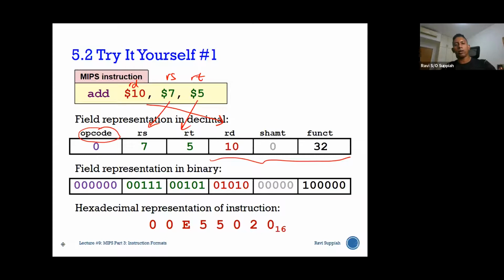So you can see that now I already have this framework for R-type instruction, and I want to extend this idea to support I-type instructions. For I-type, we know that I need opcode, I need 2 registers, correct? And then I need the immediate value. Since opcode is fixed, registers, the sizes are fixed. Opcode is 6 bits, this is 5 and 5. That means 16 bits I need. Correct. That means I now have another 16 bits that are freed up for me to hold the immediate value.